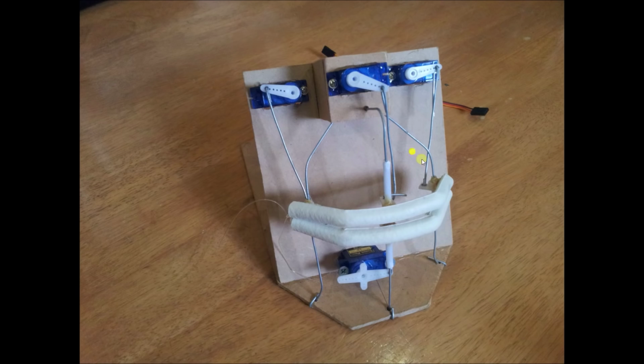for each of the connecting points used. The 2 servos on the outside control the corners of the mouth. One servo at the top controls the centre lip of the top. One servo at the bottom controls the centre of the bottom lip. And this all is then attached in behind the main frame.